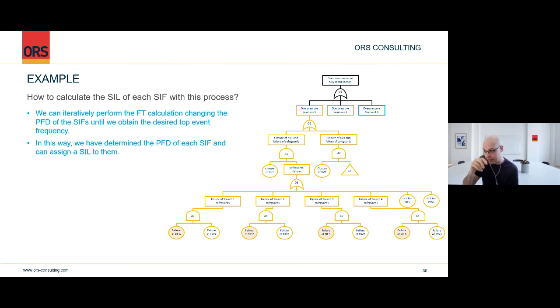The system is existing and they already know the SIF they have there achieves SIL 1, and they have a PFD of whatever X, and so you know you have X here, and what you calculate then is you just calculate whether you achieve tolerability, acceptable risk target or not. So, however, through trial and error, through an iterative process, you will find the exact PFD of each SIF.